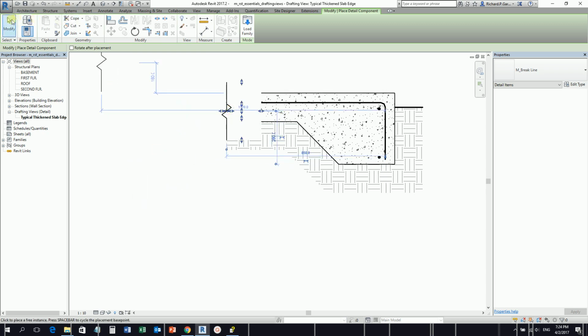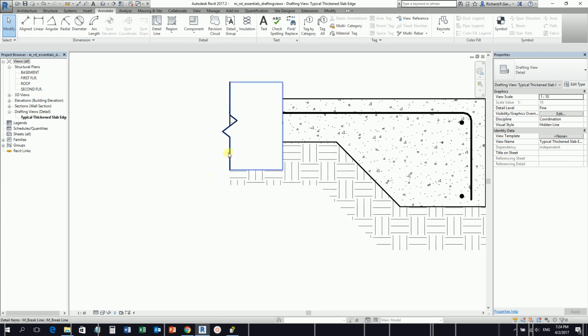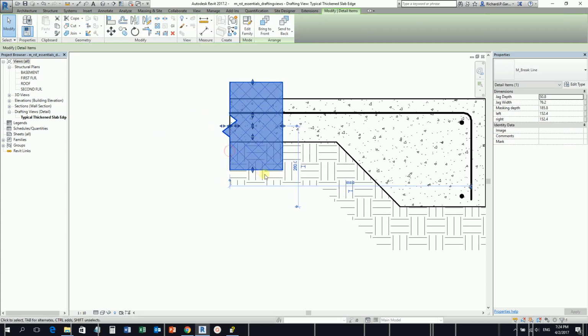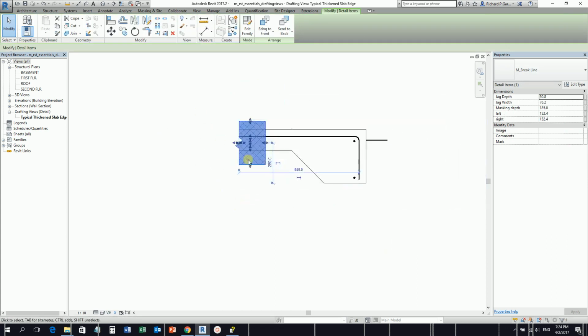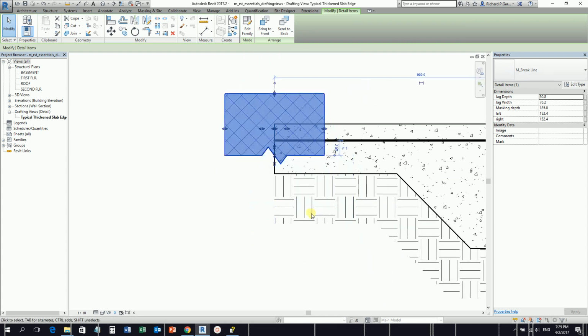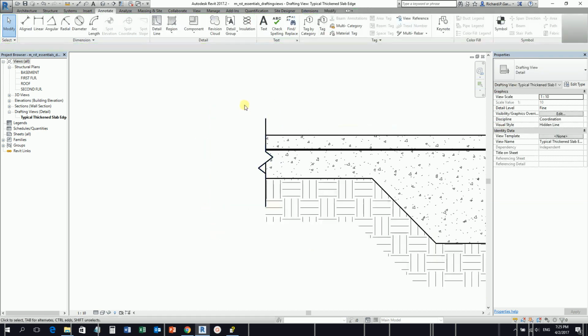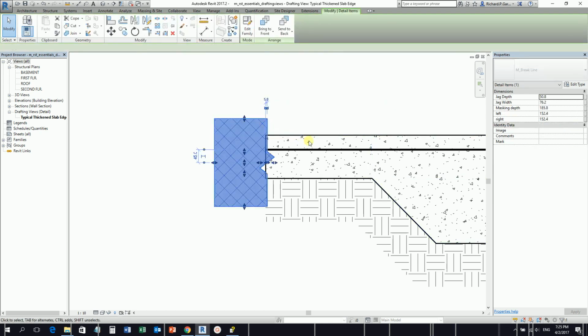There you go. And then I select here modify. Now, if it looks like this, I'm going to select the break line, and then I'm going to flip this one. Okay. Space bar. You just need to press the space bar to flip your break line. So I'll just click this one, and then I just move using the arrow on my keyboard.